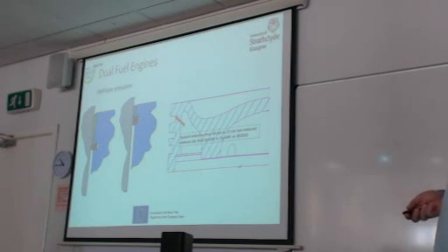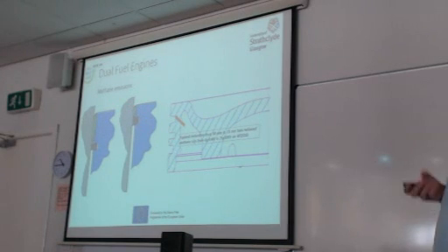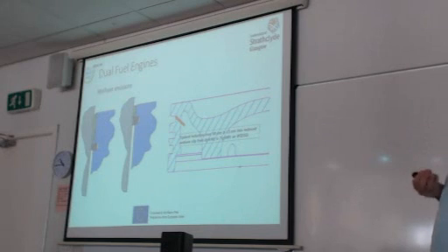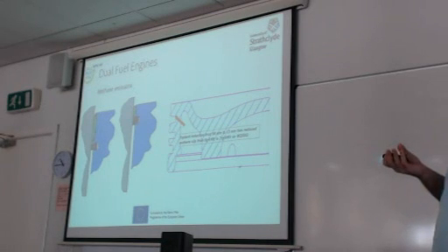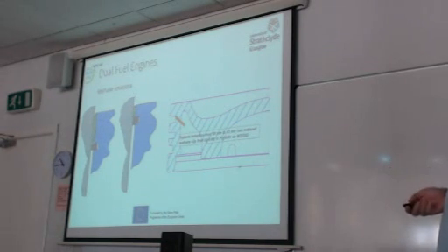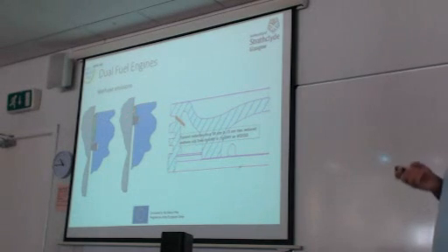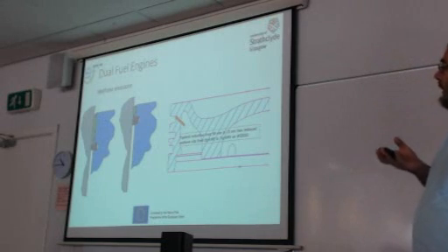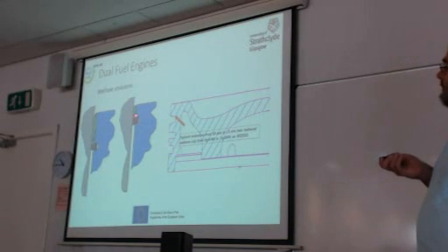increase. But actually, the manufacturers, when they started working on this concept of dual fuel engines, modified the design. They moved the ring to a higher level of the piston skirt area, and that decreased the volume of crevices, decreased the gap, so that resulted in an acceptable level of burnt hydrocarbons.